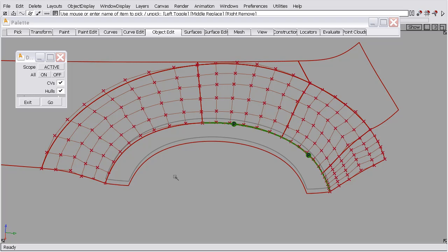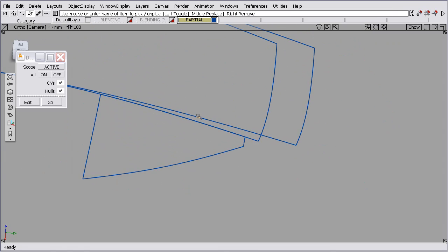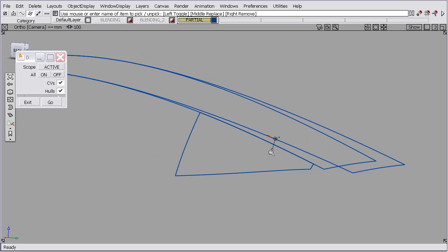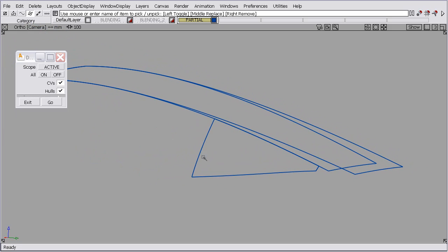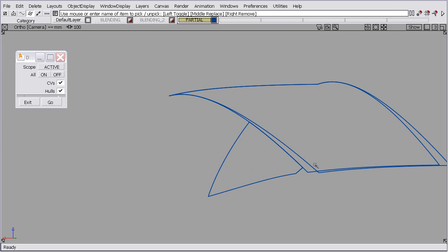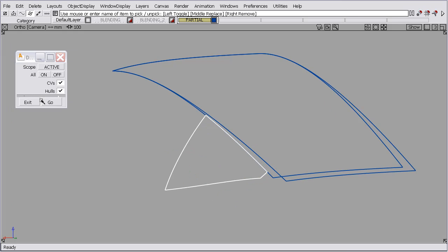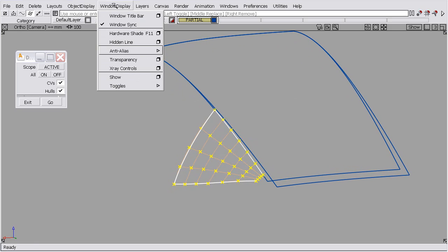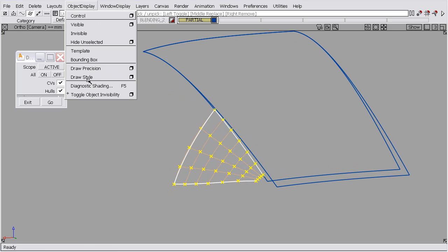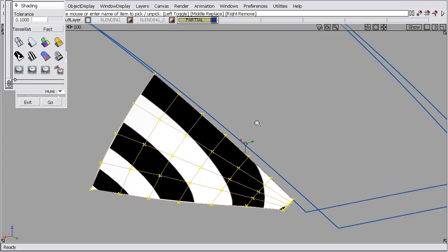Okay, now I'd like to show one more use of the blending options inside the Align tool. In this scenario, I have a roof surface and a sail panel. A design change has been requested that modifies that roof shape, but I've already spent a lot of time tuning the shape of this surface. So I'll turn the control vertices on, and I'll turn on some quick shading just so we can see a little bit that the surface has some specific shape.